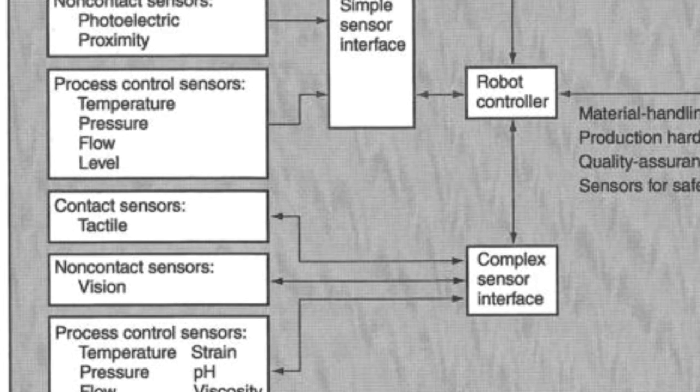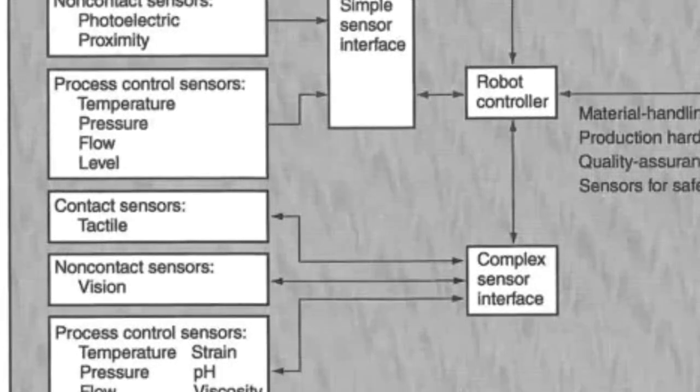So once the temperature gets above that threshold, it would send out a 1 basically to the controller, or a high voltage. Okay, 24 volts if it's a DC digital sensor. So it'd send out a positive 24 volts to the controller if the temperature was above whatever particular threshold that sensor was set for. If it's below that, it would be sending out 0 volts.